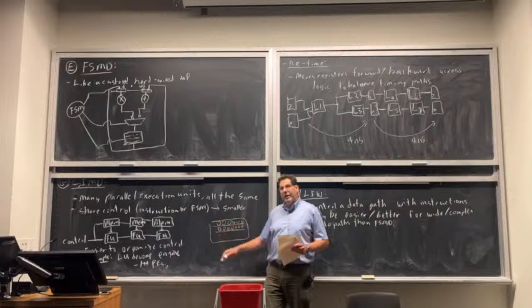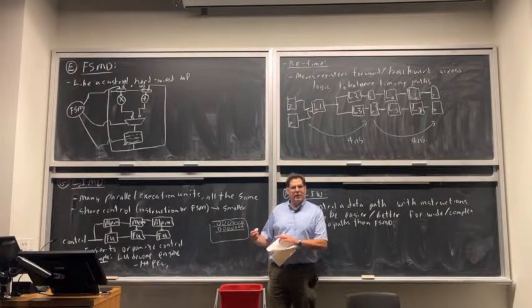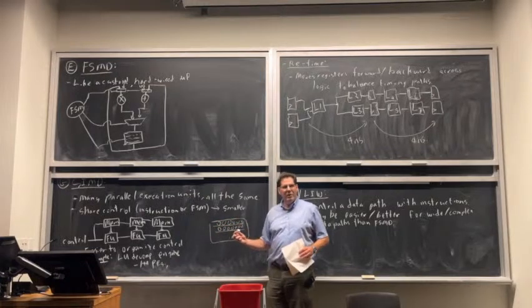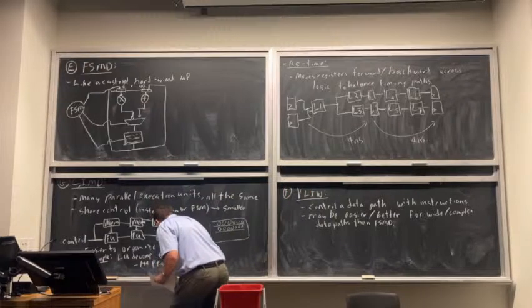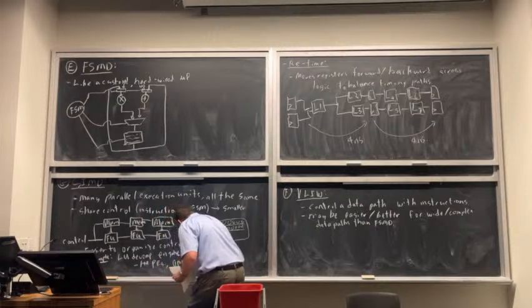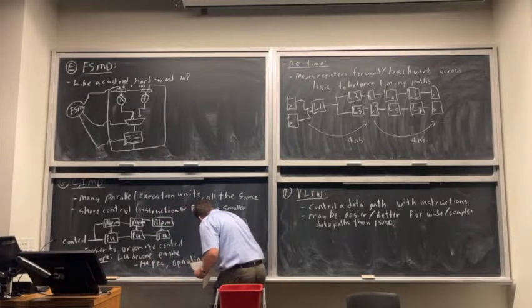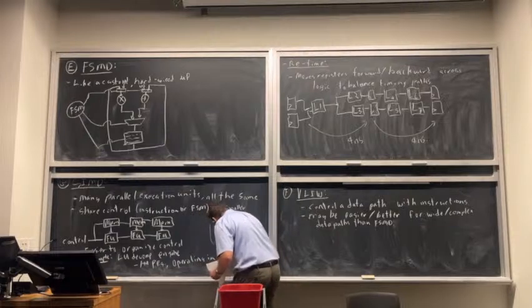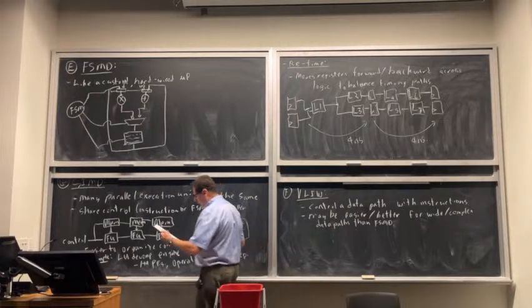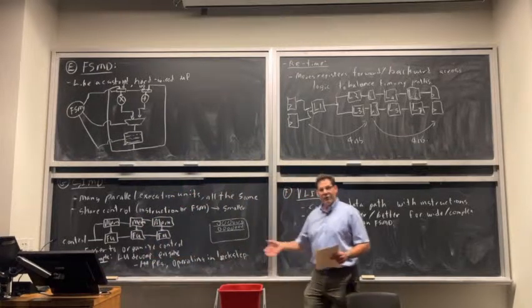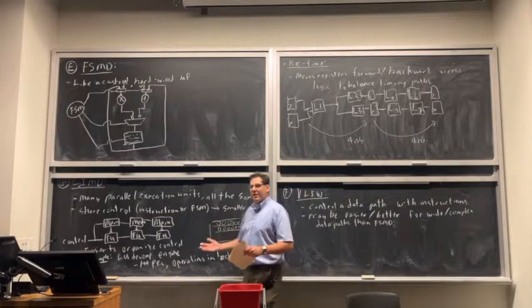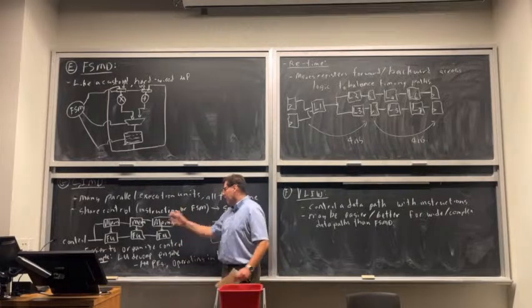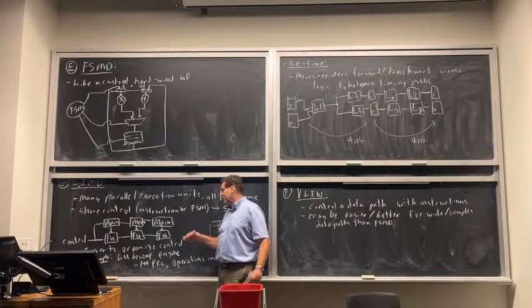It was also easier to think about, right? By doing it this way, having all the processing elements working in lockstep, just on different elements in a row, it was a lot easier to think about what that means. Some other ways of organizing the hardware might have been more difficult to control. Okay, so it's 144 PEs, and they were operating in lockstep. Okay, so SIMD is used by processors and GPUs as well, so this is a general hardware concept, but it's not limited to them. You can use it when you're designing hardware by just realizing I'm working on a lot of parallel data, it's all in lockstep, I'll make my control do that.